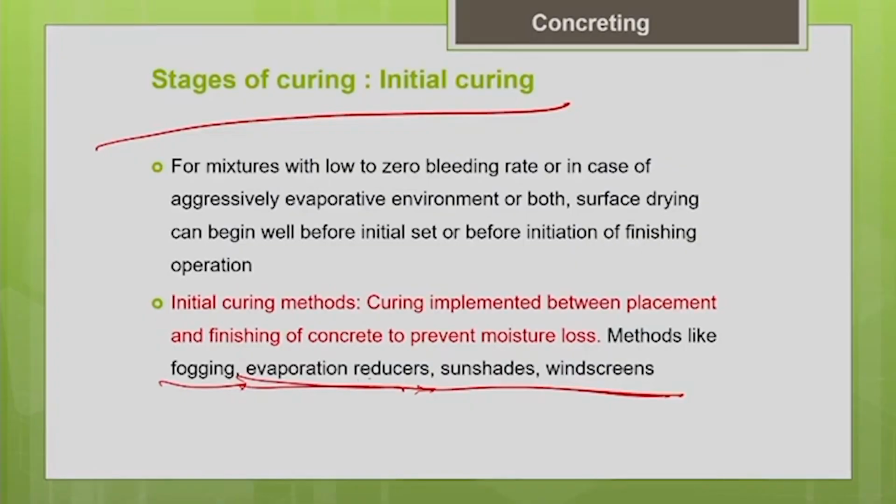They are effective only for some period of time. So, you should not confuse this with the curing compounds which we use for final curing. This lasts only for a shorter time. These chemicals will be effective only for a shorter time, so you should keep reapplying depending upon the aggressiveness of your environment.